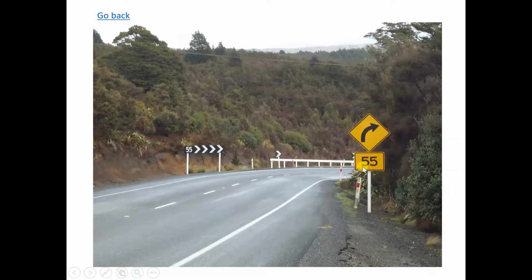Both horizontally and vertically, if it's 55, it's because the site doesn't allow a higher design speed. Generally it may be 80k, but in certain places you cannot achieve that. You probably have to put up a sign saying that for this part of the curve you need to slow down to 50k, 55k.